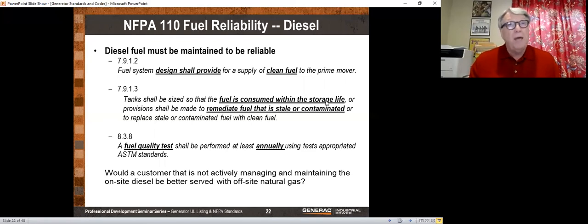Most people don't do that. And when I'm giving this presentation in person, I get to that point, and a lot of times I see people look at their buddies going, "Did you know that?" Well, you need to do that annually, and then you need to maintain the fuel. You need to check to see how much water is in the fuel.